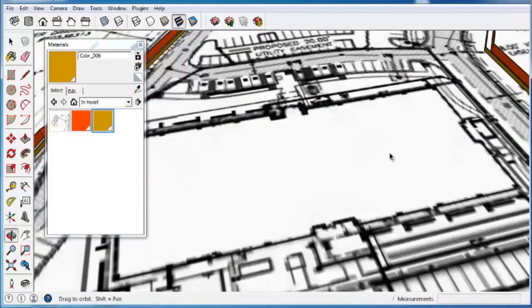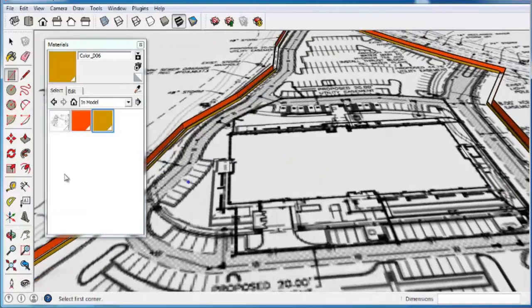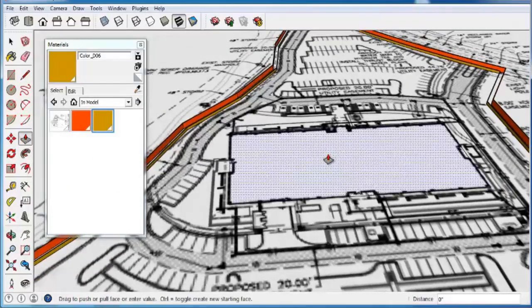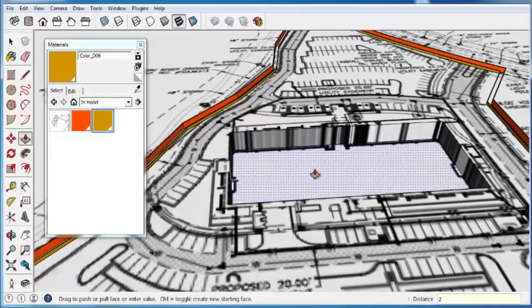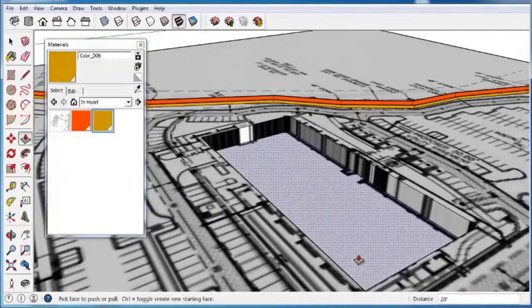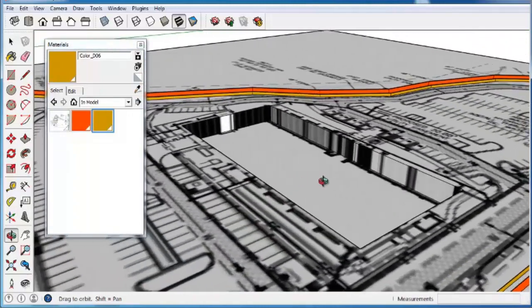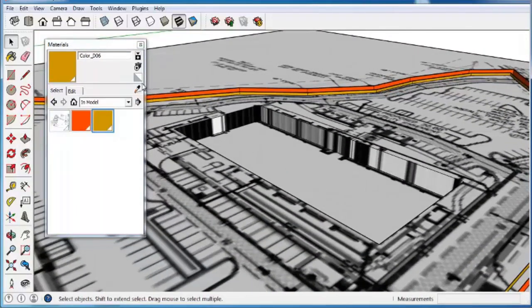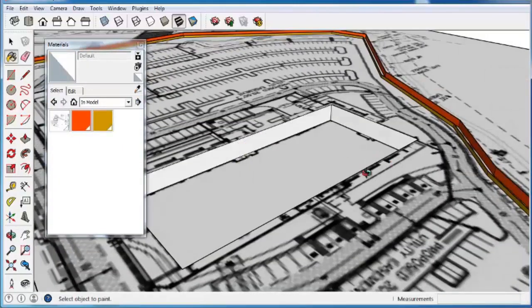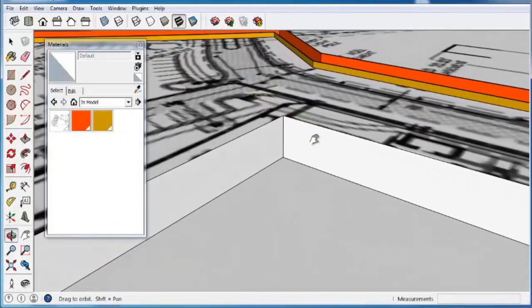What that would allow me to do here is I'm going to take my rectangle tool, I'll click once and visually make my second click here, and let's go ahead and push-pull that down, let's say 20 feet. Okay. So now I actually have used the texture in this geometry to help me model. What you see here is just warping of the image itself. I'll click this button to apply the standard default textures so I have a better idea of what I'm looking at there.